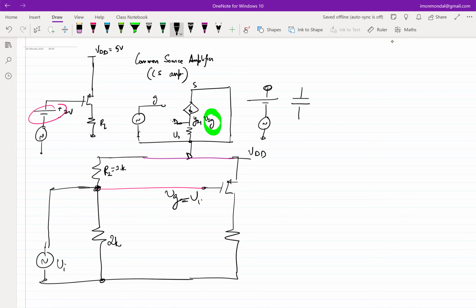Oscillating is not a very bad thing, right? Ultimately, your input is oscillation. I mean, input is a sinusoidal waveform, that's what you want. But the problem here is that this is a zero mean signal, right? Generally, it's a sinusoid, which is a zero mean signal. Zero mean signal means DC quiescent is zero, isn't it? But you want the quiescent here to be 2 volt. So you have to lift the quiescent. The battery was lifting the quiescent earlier. Now we don't have the battery, it will not be able to lift. So we are putting the capacitor to lift the quiescent.